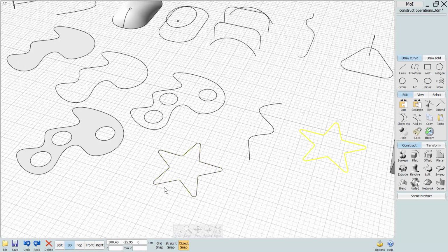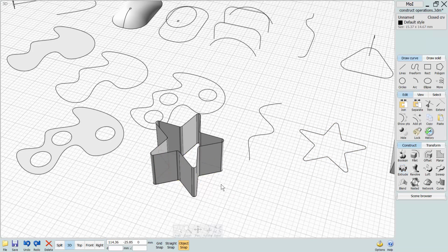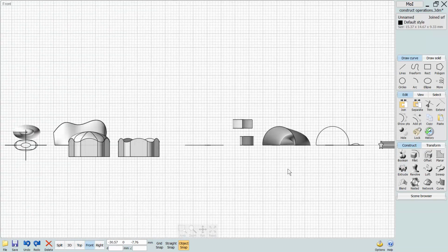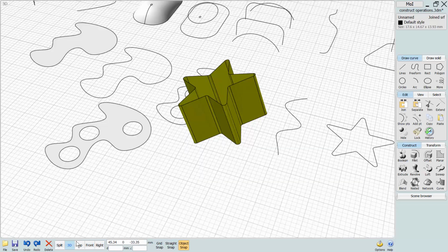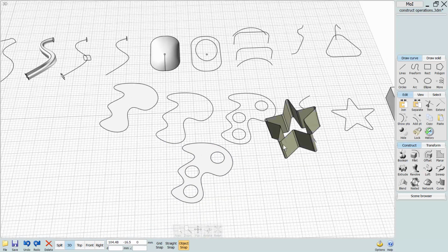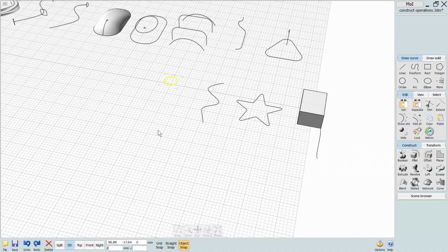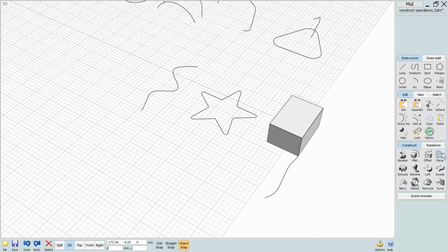Also, if you have a surface with flat openings like this, and you don't need to have it in this orientation, you can rotate it at any angle, let's say like this. And now if you select this and hit planar, Moi will cap all those flat openings, so you have solid mesh in this case. So that's how you use all those options with planar tool.